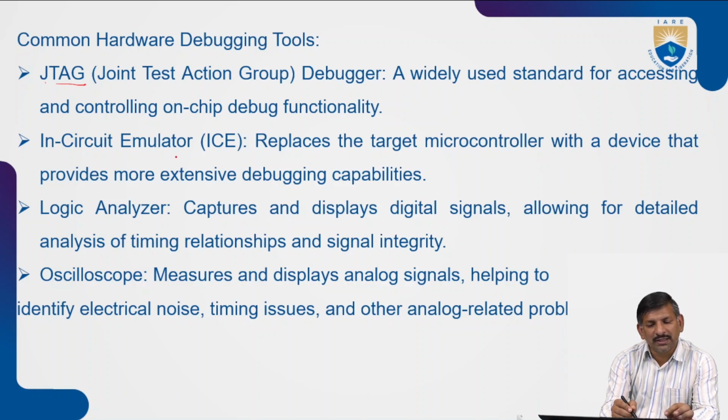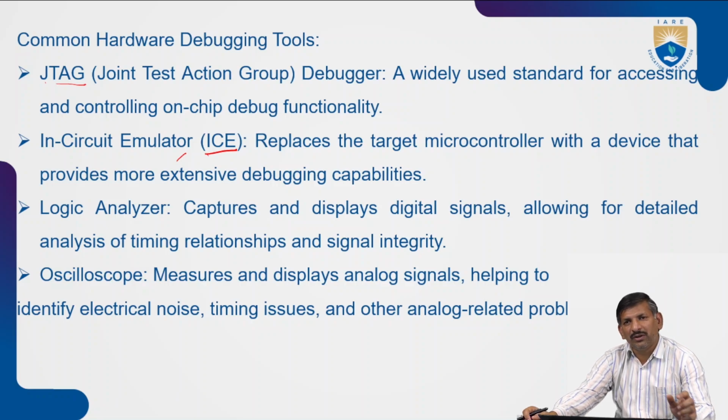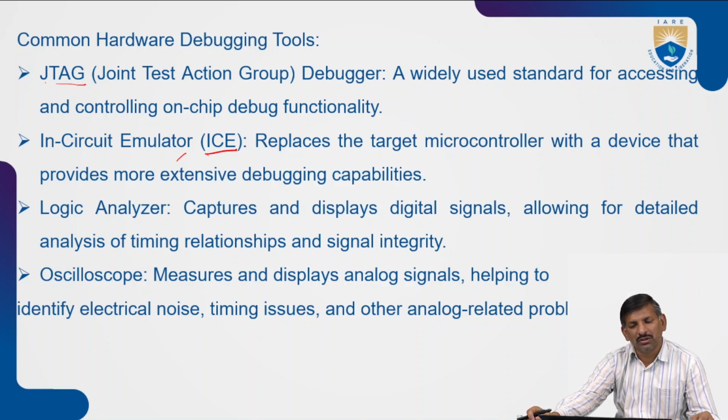Another one is in-circuit emulator, ICE. It replaces the target microcontroller with a device that provides more extensive debugging capabilities. So during the development stage, if you are using original hardware and it fails frequently, we have some problem. So instead of that, we can use an in-circuit emulator to check whether it is working in the desired manner or not. Emulator emulates the hardware functionality.